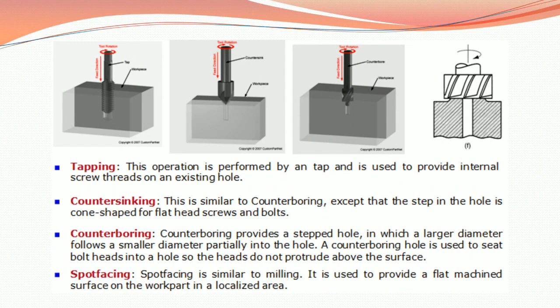Countersinking. This is similar to counterboring, except that the step in the hole is cone shaped for flat head screws and bolts. Counterboring. Counterboring provides a stepped hole in which a larger diameter follows a smaller diameter partially into the hole. A counterboring hole is used to sit bolt heads into a hole so the heads do not protrude